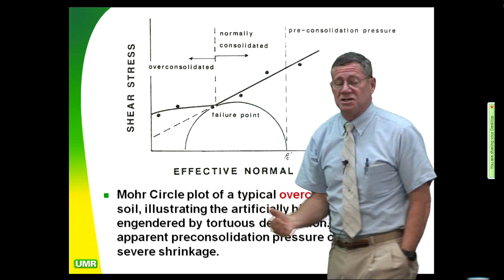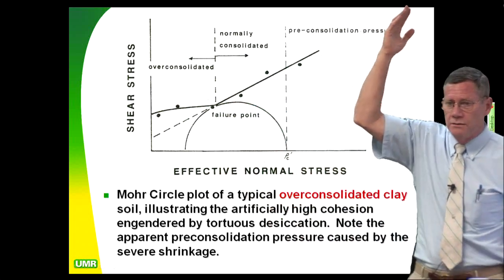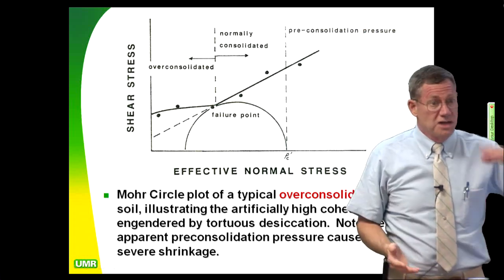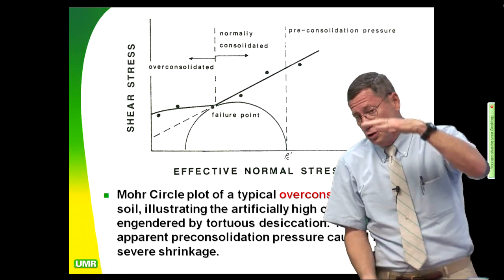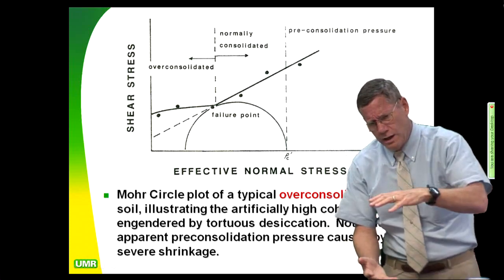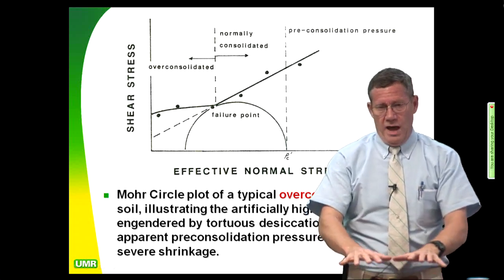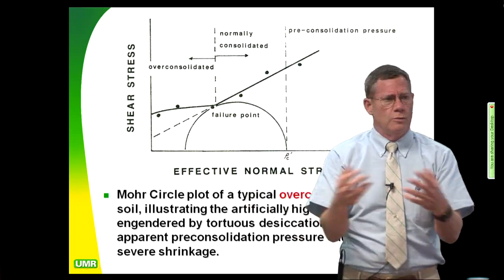Now, you get to places like Cleveland, where they had glaciers 3,000 feet thick going up the Cuyahoga River Valley. That's really overconsolidated clay. That clay has had this huge load on it that's melted away into Lake Erie, and now that clay can rebound with the removal of that glacial load and absorb more and more water.